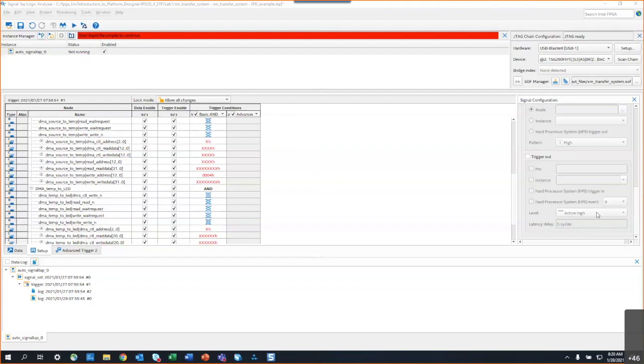Right. But it is not that way. Every clock cycle of the signal tap, the data keeps changing, even though I expect, because the ADC updates data at half the rate, that it wouldn't. I hope that makes sense.